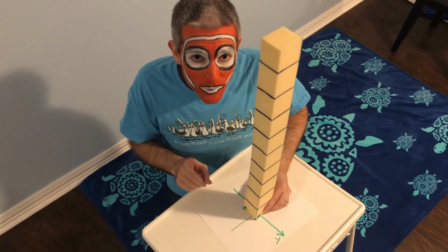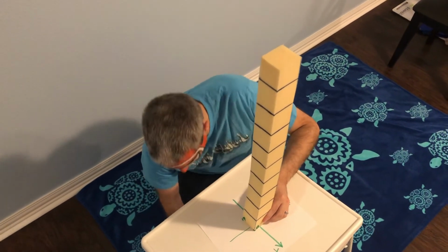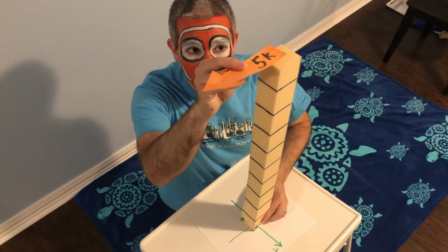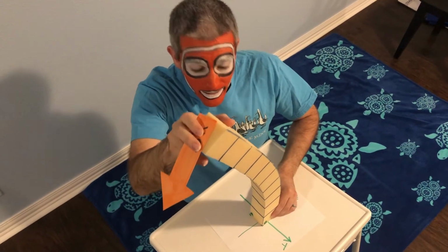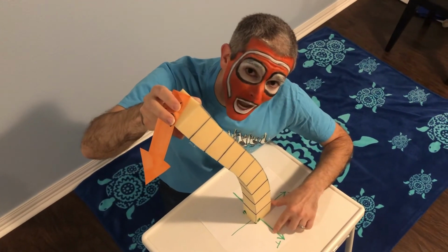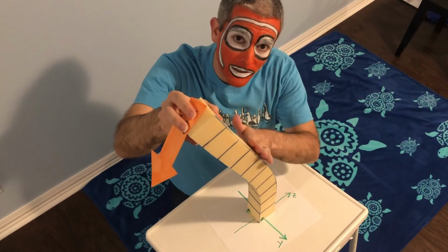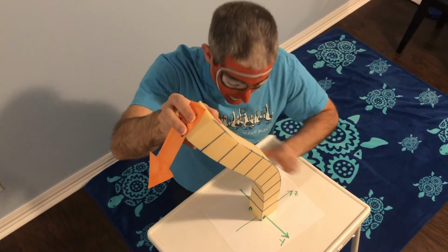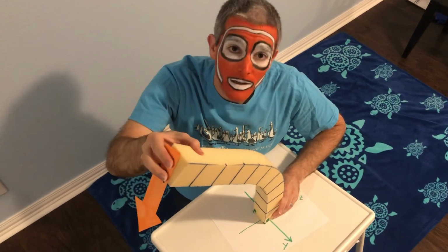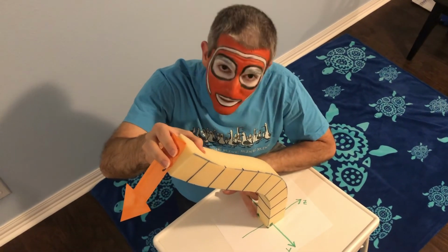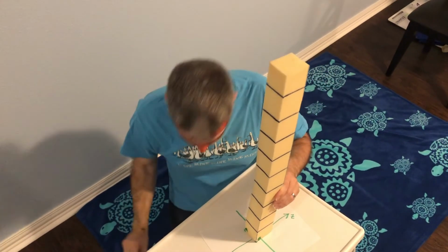All right, so the first force we want to examine is the 5-kip force in the negative Z direction. If we apply that 5-kip force, we'll see that it's going to cause the column to bend about the y-axis. As it bends, we get tension along the backside and compression on the inside. So down here at points A and B, we see that this force causes compression at both points A and B.